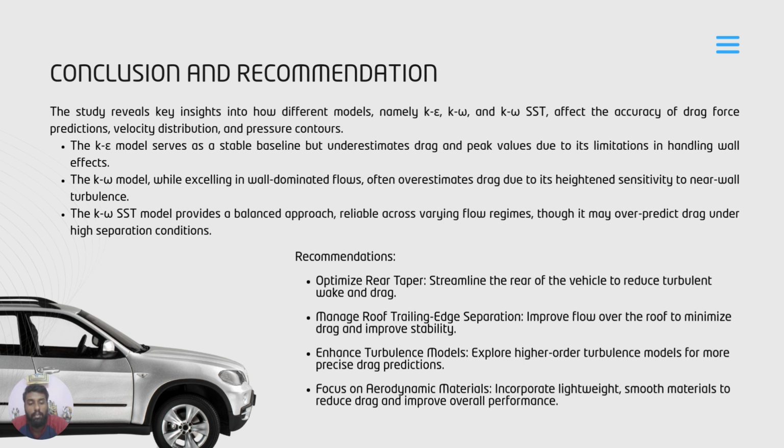The recommendations are: optimize rear taper, streamline the rear of the vehicle to reduce turbulence, wake and drag. Manage roof trailing edge separation, improve flow over the roof to minimize the drag and improve stability. Enhance turbulence models, explore higher order turbulence models for more precise drag predictions. Focus on aerodynamic materials, incorporate lightweight, smooth materials to reduce drag